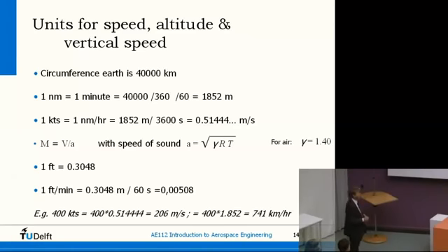And of course, you can also calculate to meters per second. Yes? Why indicate the speed in how many times the speed of sound? Because, for one thing, it's a handy measure for higher speeds. And the other thing is that it dramatically changes the flow around an aircraft when you go transonic or supersonic. Then the aerodynamics are completely different.